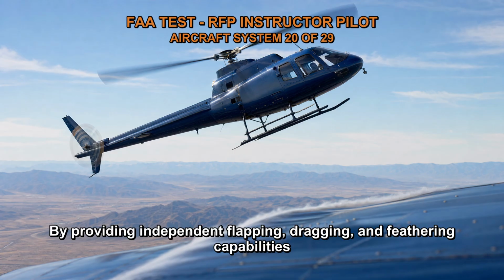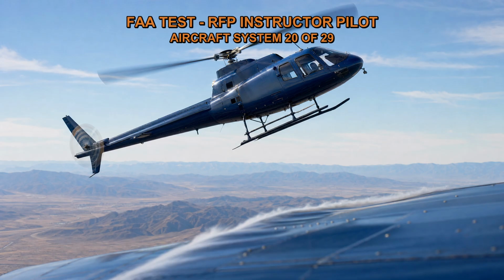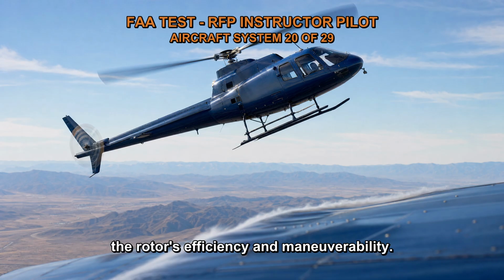By providing independent flapping, dragging, and feathering capabilities to each rotor blade, a fully articulated rotor system offers enhanced control, stability, and performance for the helicopter. This design allows for precise adjustment of each blade's position, pitch, and angle of attack, optimizing the rotor's efficiency and maneuverability.